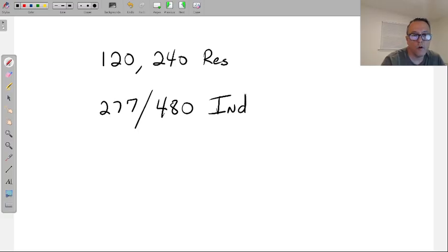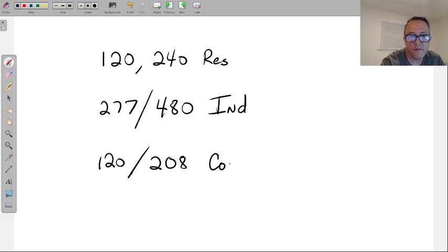There is one more. It's actually the one that's very, very common for commercial buildings. In fact, the building that you guys are in right now has this voltage, which is 120, 208. Oops, sorry about that. Hey, one more. There we go. And this is usually found mostly only in commercial. However, sometimes industrial will use it.